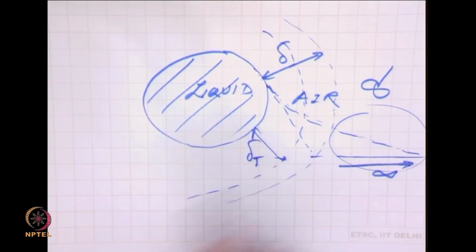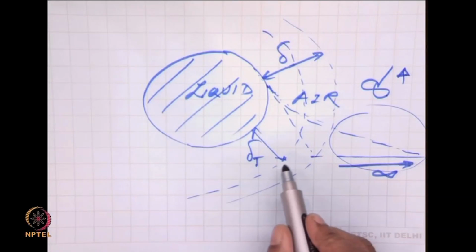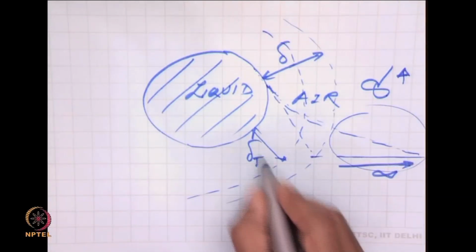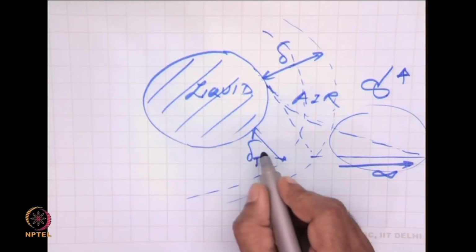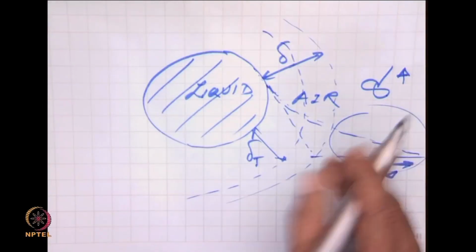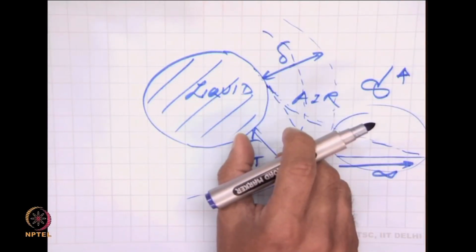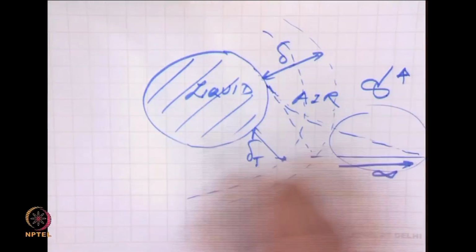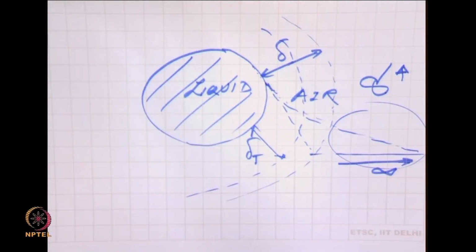Let us say we call it delta T. Greater the intensity of this mixing, or greater the intensity of turbulence here, thinner will be this stagnant film of film theory, delta T will get smaller, right, which means the resistance which is attributable to this gas film will get reduced as you increase the stirring. Resistance gets reduced, therefore, the rate of evaporation will be higher. Now, that is common, right. It is analogous, that example of dissolving sugar in a cup of tea by stirring is an analogous example.